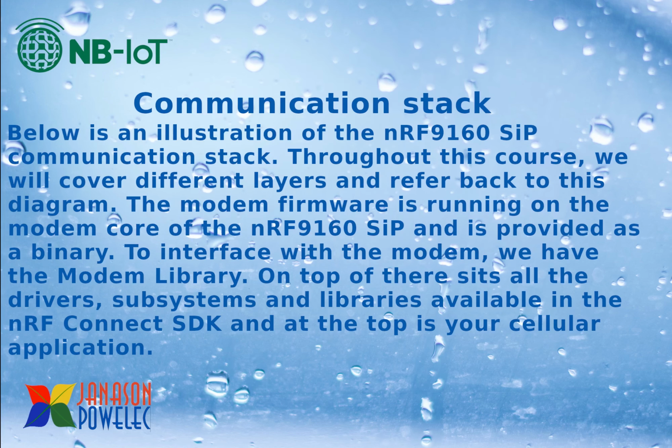Communication stack. Below is an illustration of the nRF9160 SiP communication stack. Throughout this course, we will cover different layers and refer back to this diagram. The modem firmware is running on the modem core of the nRF9160 SiP and is provided as a binary. To interface with the modem, we have the modem library. On top of that sit all the drivers, subsystems and libraries available in the nRF Connect SDK, and at the top is the cellular application.